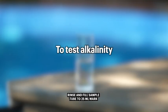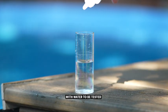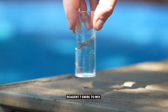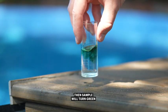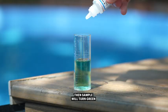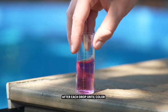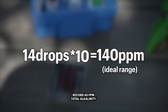To test alkalinity, rinse and fill the sample tube to the 25 ml mark with the water to be tested. Add 2 drops of reagent 7, swirl to mix. Add 5 drops of reagent 8, swirl to mix, and then the sample will turn green. After that, add reagent 9 dropwise, swirling and counting after each drop until the color changes from green to red. After that, multiply drops in step 4 by 10. Record as parts per million total alkalinity as calcium carbonate.